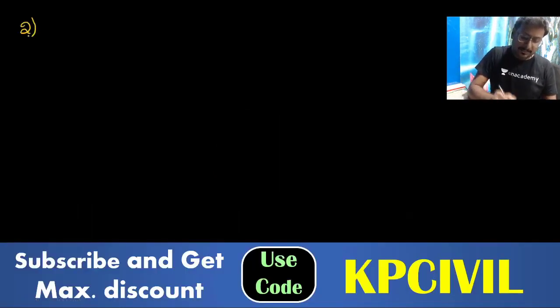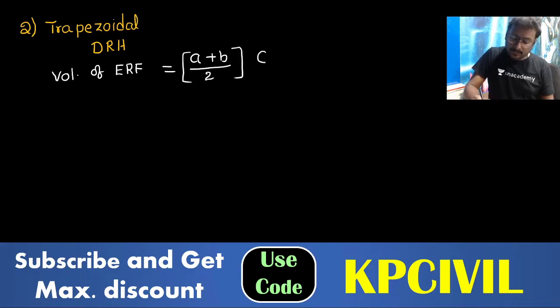Second one we'll consider: trapezoidal DRH, a direct runoff hydrograph which is trapezoidal. So what is the volume here, the area of DRH or volume of effective rainfall? For a trapezoid, we can write (A plus B) by 2 into peak discharge.